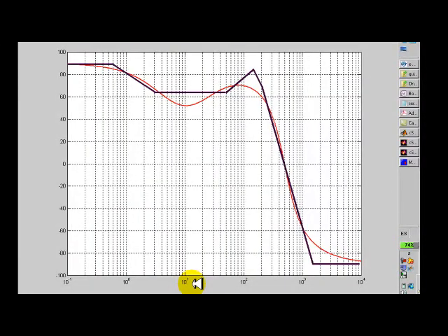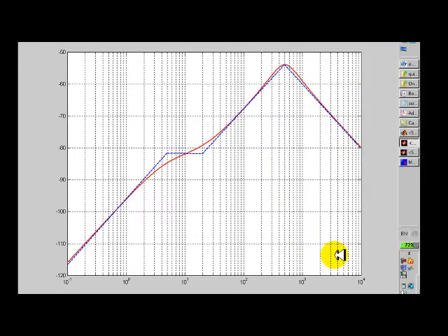This is the approximate solution now on semi-log paper, the one we computed before, and as a reference I have plotted also the exact phase of that transfer function for each one of the frequencies of interest. However, this red curve was not part of the question in your exam, only the black segmented line. The exact amplitude of the transfer function versus the approximate one that we computed in blue can be seen here.